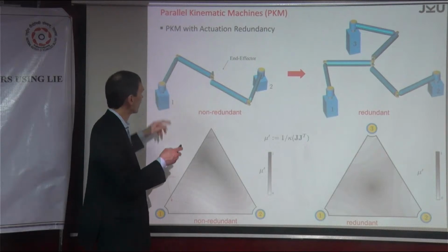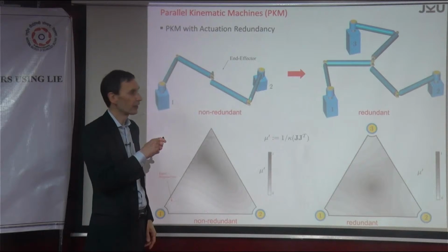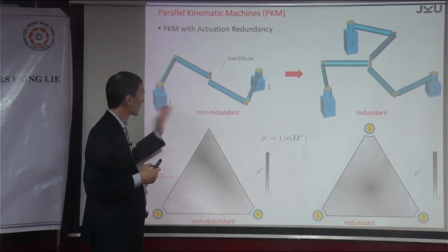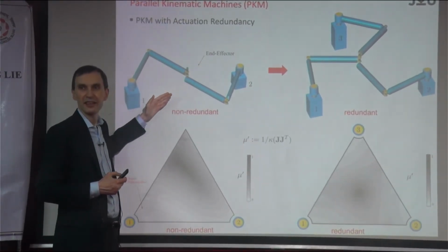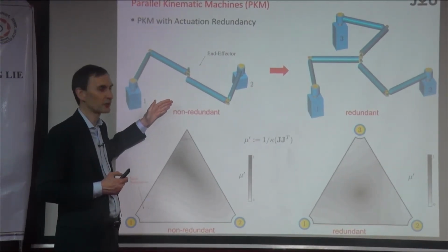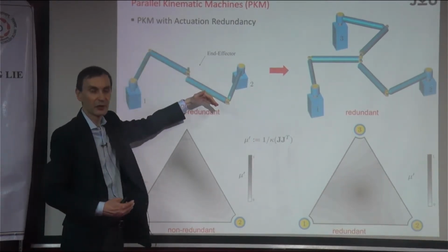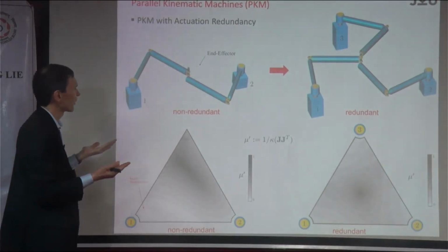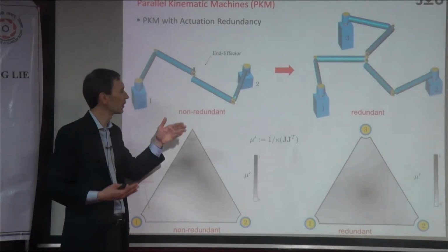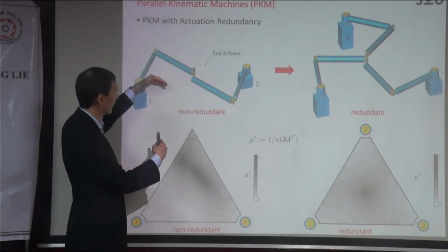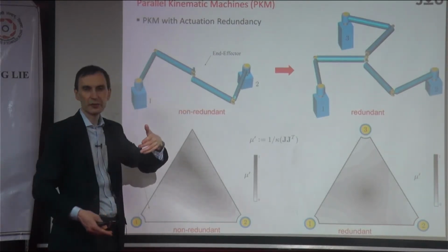What I'm asking is, the motors, the inputs are here, this one and that one. So the question is, can you generate a motion in this direction? No, you cannot. Because if you move this one and this one, whatever happens, you only go this way, right? Because they are just aligned. I know it's very simple, but that's a very special case of a so-called singularity. So you cannot generate motions in this direction. If this is not aligned, then you always can.